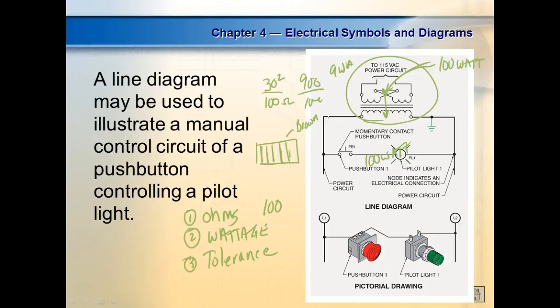So yeah, we got different tolerances between the 10. The 20, which you don't hardly see anymore, didn't have a tolerance band. So we said the 20%, we called it a neutral color or transparent. And then we have silver, which is what? 10%. Then we have gold, which is 5%. And that's the predominant percentage.